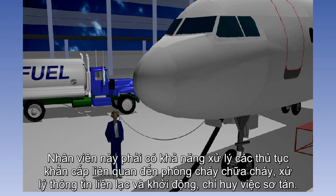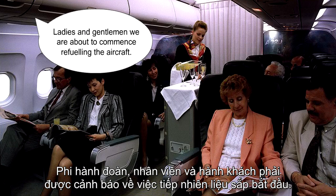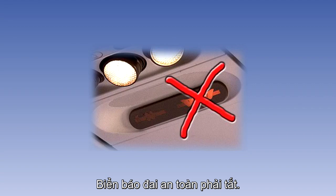This qualified person must be capable of handling emergency procedures concerning fire protection and firefighting, handling communications, and initiating and directing an evacuation. Crew, staff, and passengers must be warned that refueling is about to take place. Seatbelt signs must be off.